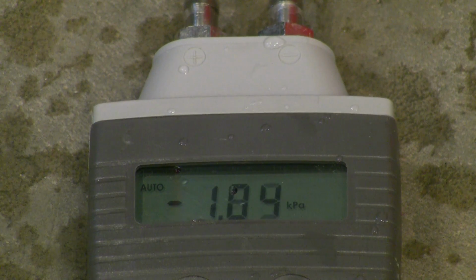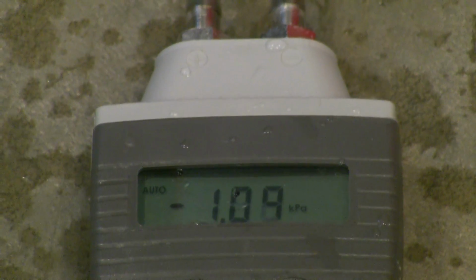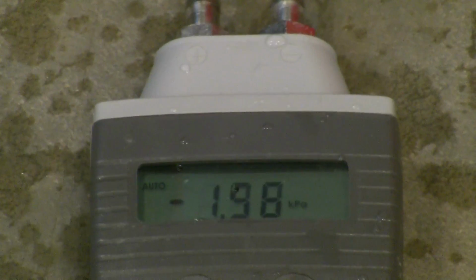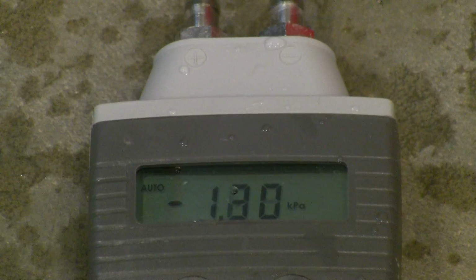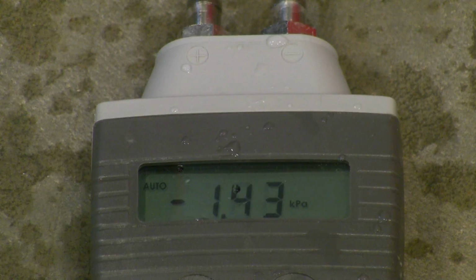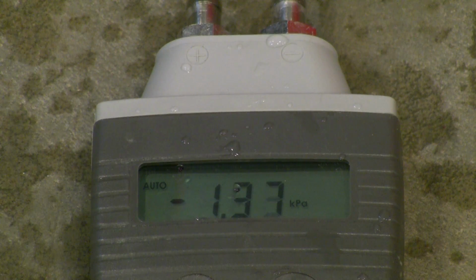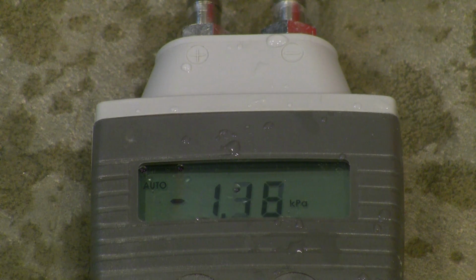It's jumping around a bit, and the way that we handle that and overcome it is with a temporal average. So you'll see several different values. Enter 5 or 6 or 10 of them into your calculator and then take the average of all of them. I'll do the same. I'll write down some values on my page, and later on I'll take an average so that I know the average drop in pressure through this fitting.